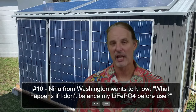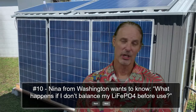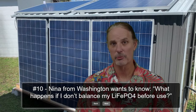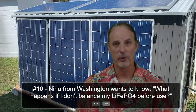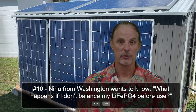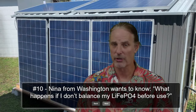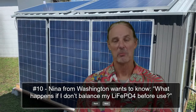Most likely, if it's a store-bought battery in today's world, nothing. You would plug it in, it would come at approximately 50% charge. You could charge it up with the system. As a matter of fact, that's what I did with my LiFePO4 batteries when they came in. I hooked all 4 of them up, they were all within 1% of each other. I connected all 4 of them in parallel, and I did my initial charge and balance from the 6000 all-in-one with the inverter turned off, so that all the power from the solar just went straight to the batteries and got them charged and reset. So in most cases, probably nothing.